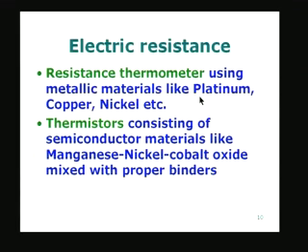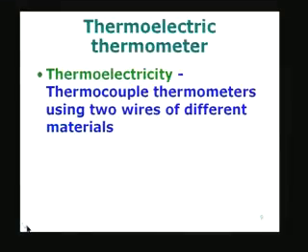In the case of the platinum resistance thermometer, exactly opposite. The resistance change is very slow or very small. The rate at which it changes with temperature is very small, but it can be used over a very large temperature range. If you recall, in the ITS 90, we use essentially the platinum resistance thermometer to measure the temperature from the triple point of hydrogen. We can go back to the slide and see what we did there.